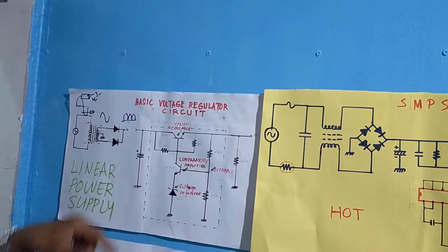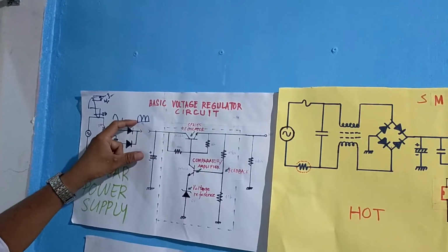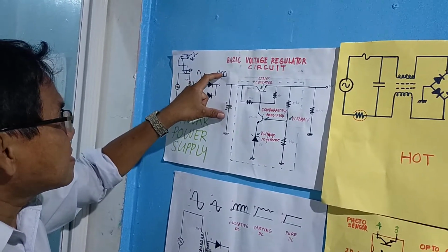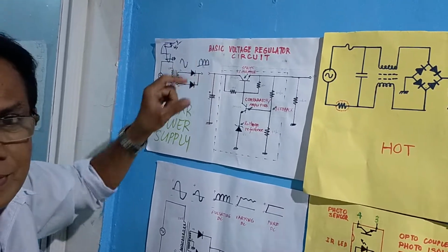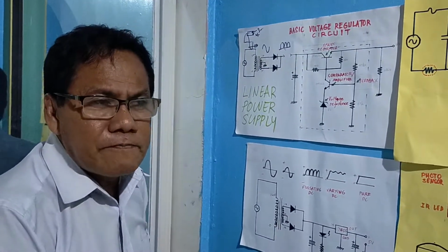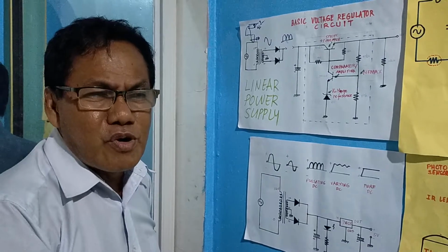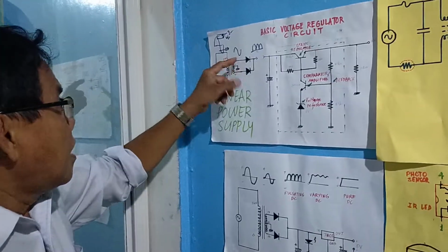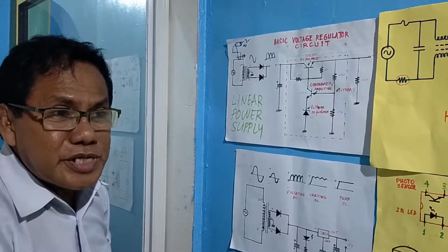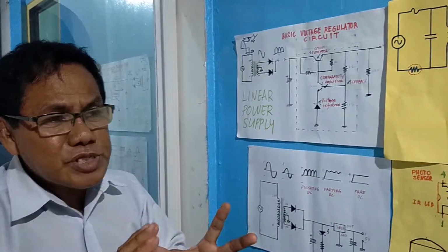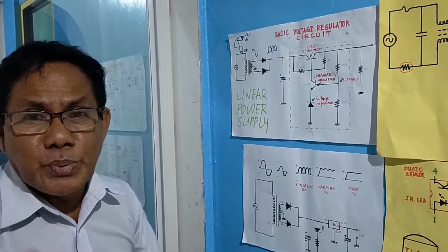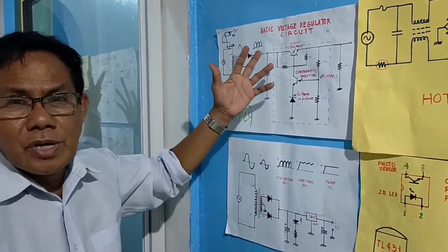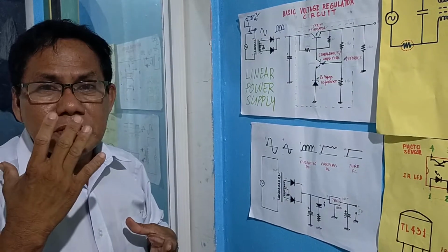It is still varying. The voltage here is 0, 12, then probably 8, 12, 8, 12. There is a gap of 6 volts. Oh no, 4 volts variation. So, once it is supplied to a certain amplifier, there are musics that you can hear, but it is accompanied with hum. That hum now is the 120 Hz, which is audible to the human ears.